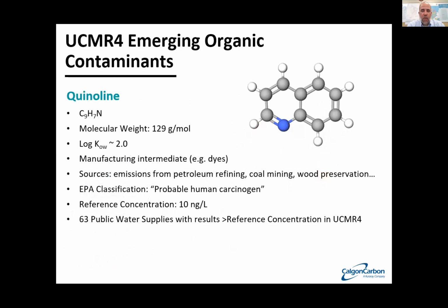So the next compound in the set is quinoline. I'll admit we didn't see this repeatedly in the influent water, so we have a sparse amount of data, but nonetheless some data that suggest what we might see at full-scale treatment. The log KOW is a little bit lower. This means it's a little bit less removable with activated carbon through straight adsorption, but it should still adsorb at that level. You can see this from numerous facilities that might be doing petroleum refining, wood preservation. Again, I can't speak to exactly why it's in this wastewater, which is for the bulk a municipal wastewater. This is not industrial wastewater.